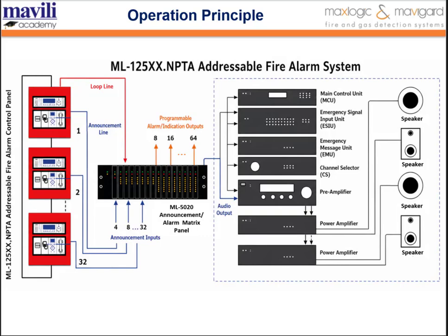Furthermore, trained personnel can use the announcement microphones or intelligent addressable fire alarm control panels to convert live messages into announcements and directly into a voice alarm and announcement system via the matrix panel channel. In other words, announcements can be made by authorized personnel via intelligent addressable fire alarm panels, even outside of cause and effect scenarios. Trained personnel can also select the area or areas to be announced via the system on the intelligent addressable fire alarm control panels.